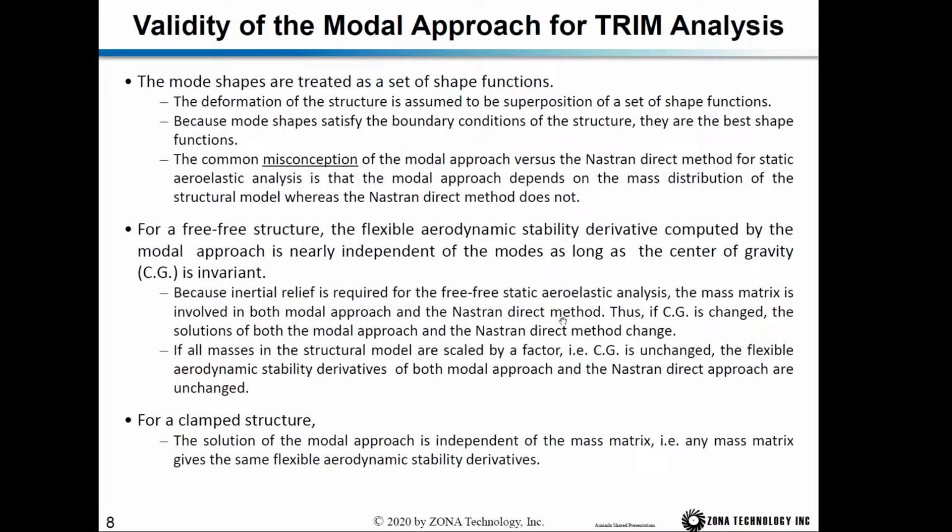And then you may ask, the static aeroelastic problem is a static problem. Why is the mode shape involved? Because mode shapes are calculated, and mode shapes depend on the stiffness and the mass of the structure. The mode shapes are treated as a set of shape functions. The deformation of the structure is assumed to be a superposition of a set of shape functions. Because the mode shapes satisfy the boundary conditions of the structure, they are the best shape functions.